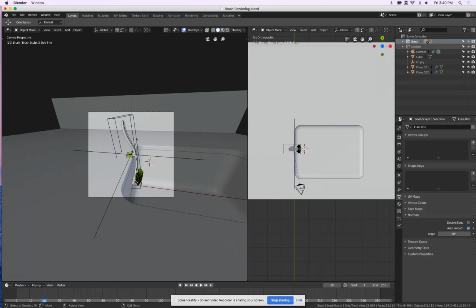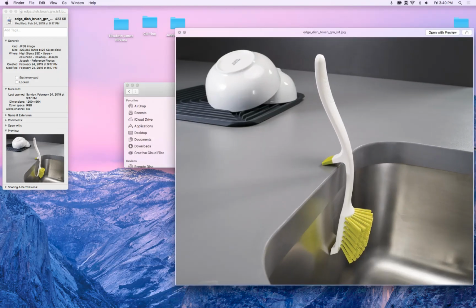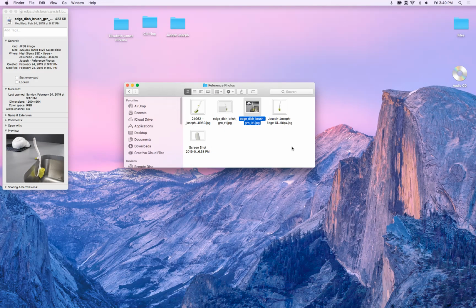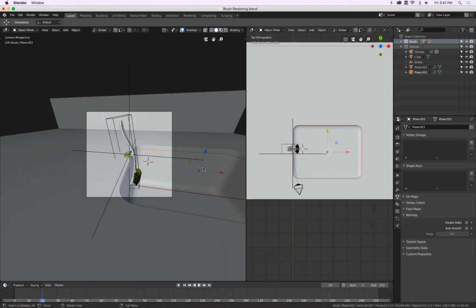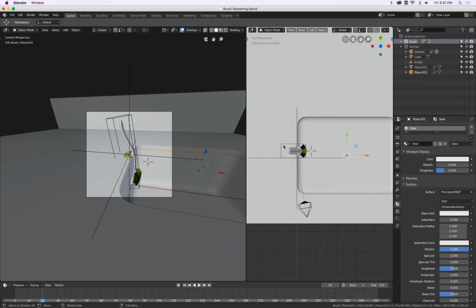Now let's take a look at the materials. That's kind of like a plastic type of material. That's a brushed metal. We will simplify each one. Throughout the semester, we will get to materials that are more and more realistic. So this sink, we make a metal, let's say steel, spelled correctly, and go to specular, 0, metallic up, and well, we leave this where it is right now.